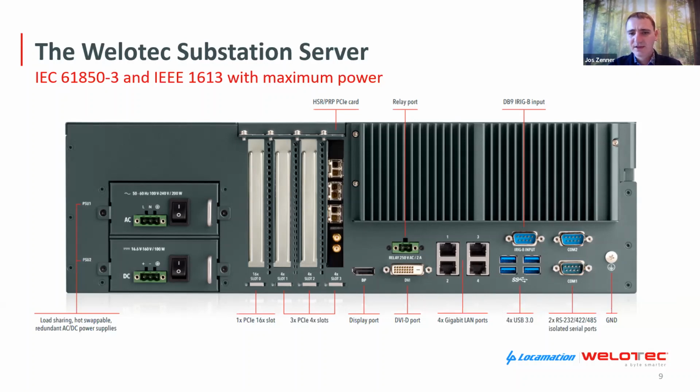And then there are 4 gigabit LAN ports, and those gigabit LAN ports can also support PTP, so they are real-time capable and capable to work with real-time applications, so that you have also precision timestamping on it. Besides that, there are USB ports, COM ports for legacy equipment, and for timing there's additional USB input.